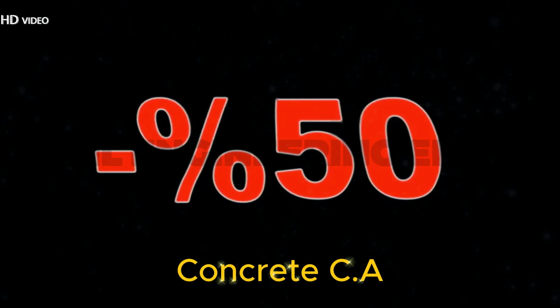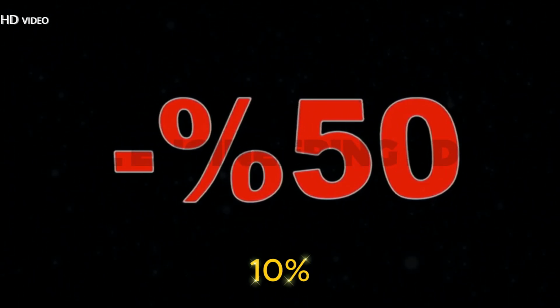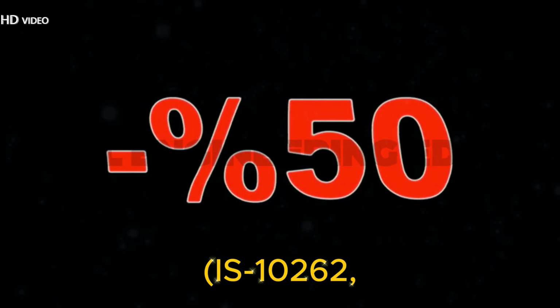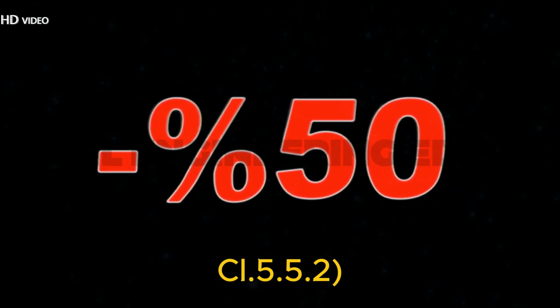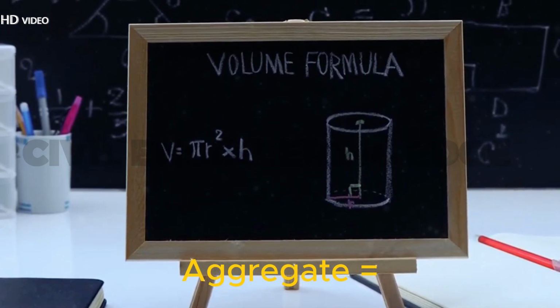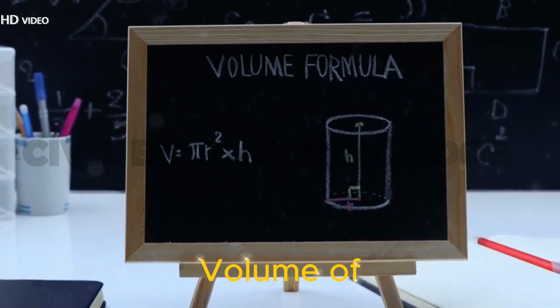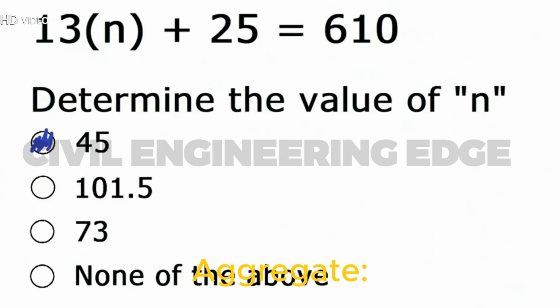Adjusted for W/C ratio 0.50, 0.61. For pumpable concrete, CA can be reduced up to 10%, so volume of coarse aggregate equals 0.61 minus 10% of 0.61. Volume of coarse aggregate, 0.549.